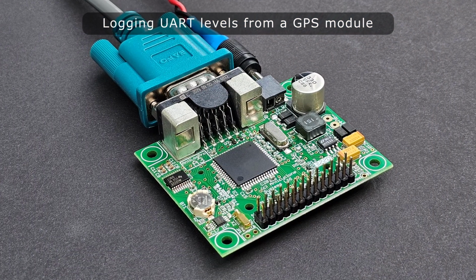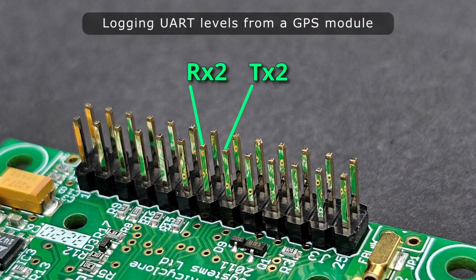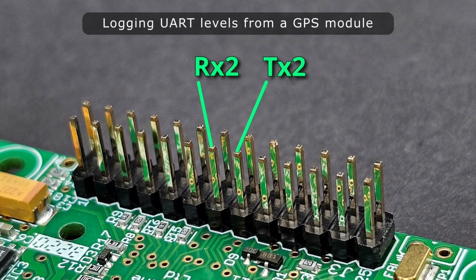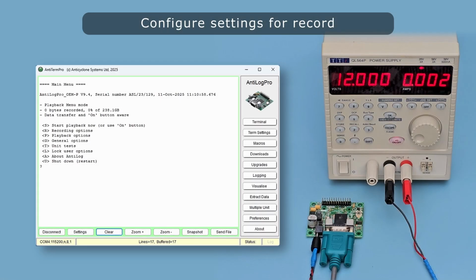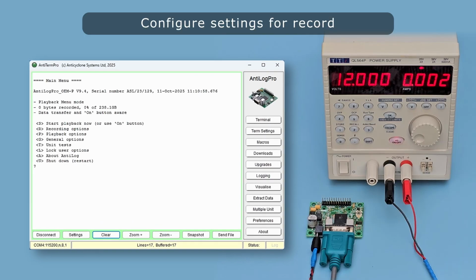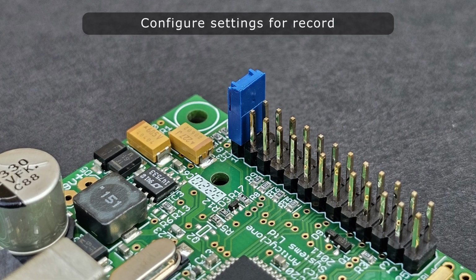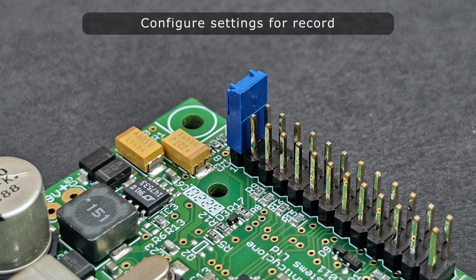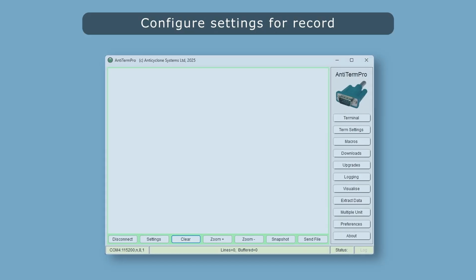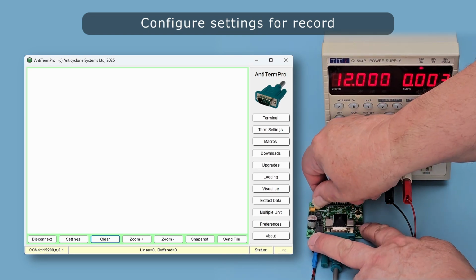To demonstrate, I will use an AntiLogPro OEM data logger, which features two such dedicated serial port connections on its application pin header. To configure this secondary serial port, start the data logger in the playback menu mode. A quick way to do this is to fit a link between pins 1 and 2 on the application header to simulate an on button. Apply power, wait 2 seconds, and remove the link.